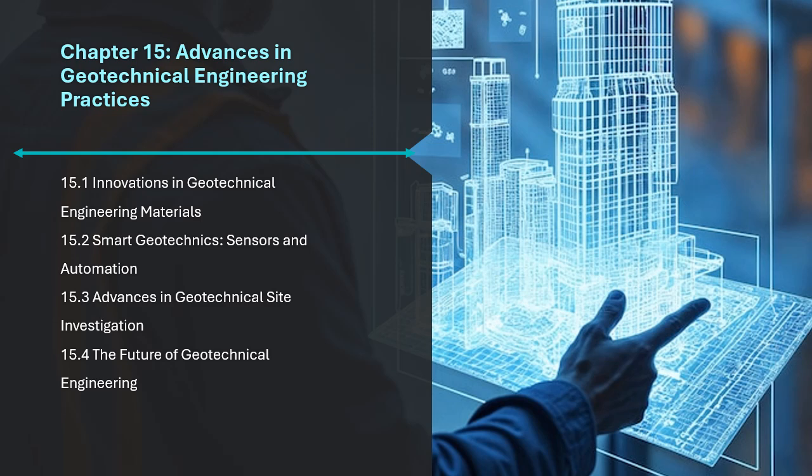Smart foundations embedded with sensors can measure parameters such as settlement, displacement, temperature, and moisture content. This real-time data enables proactive maintenance and design adjustments during the construction phase or throughout the lifespan of a structure. For example, smart foundations can monitor the health of buildings, bridges, and dams, alerting engineers to potential issues before they become critical.